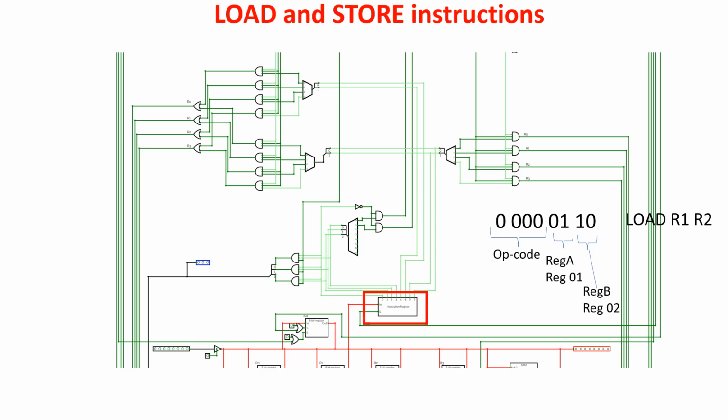The Scott CPU operates only with the 4 registers from R0 to R3. So we need 3 decoders 2 to 4 to manage the 4 registers. In the blue ring we see the decoder to select the register A. We only give an enable pulse to register A to put a byte on the bus. In the red ring, the 2 decoders for selecting register B. We give an enable pulse on the left and a set pulse on the right to acquire the result of the operation and put it in register B.